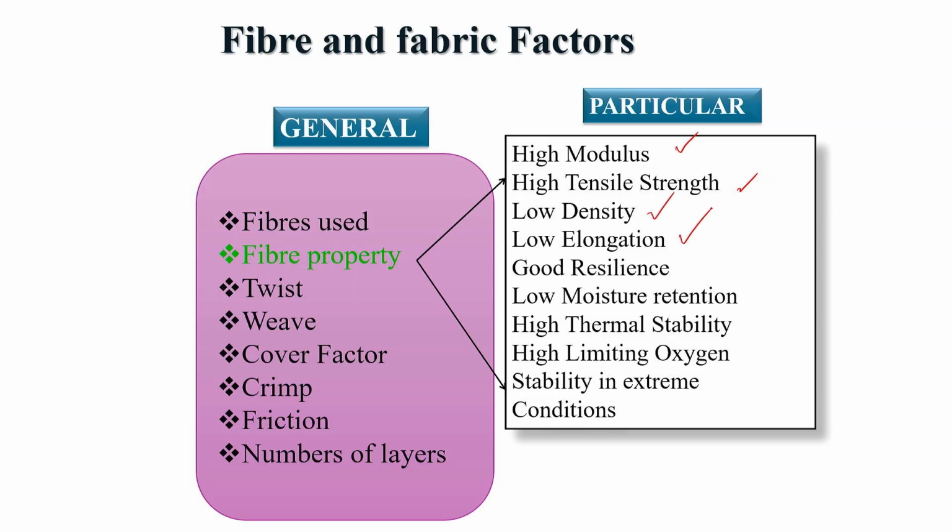Elongation should be lower, it should have good resilience in tensile deformation, low moisture retention capability, high thermal stability, high limiting oxygen index and stability in extreme conditions.